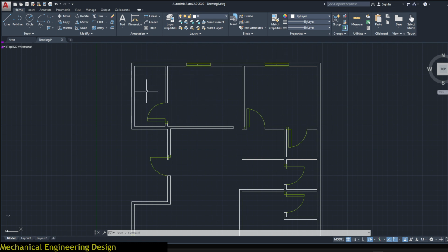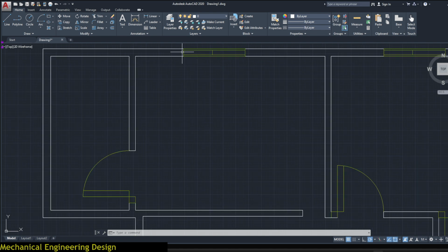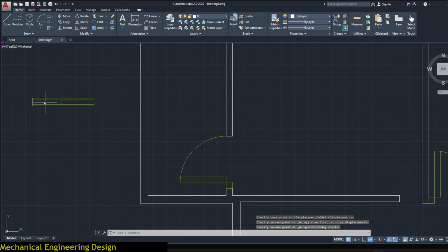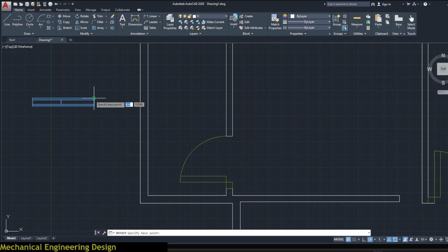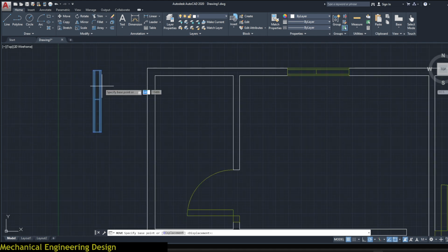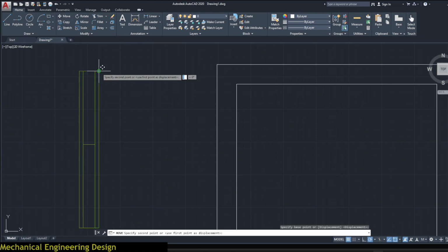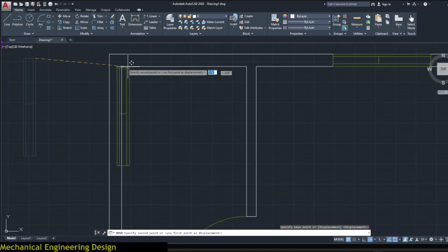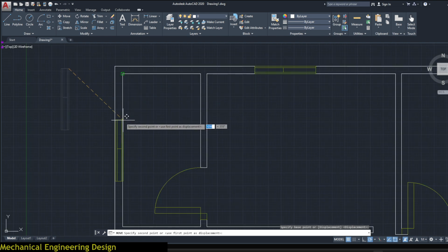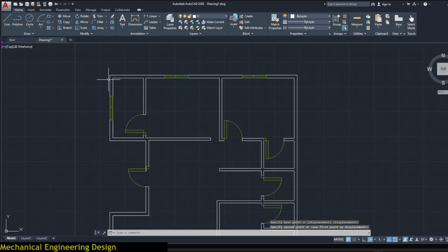We also have to put 1 here on this wash area. Just click and copy this point, right click and enter. Select, then rotate 90 degrees like that. Select, then move. We'll select the top corner here. Come to this point, drag it downwards. This point, like that.